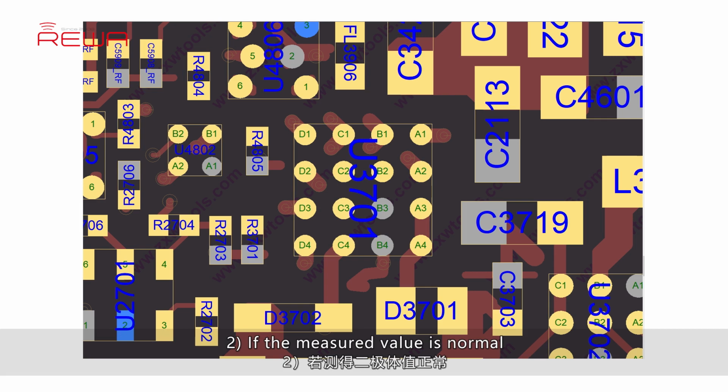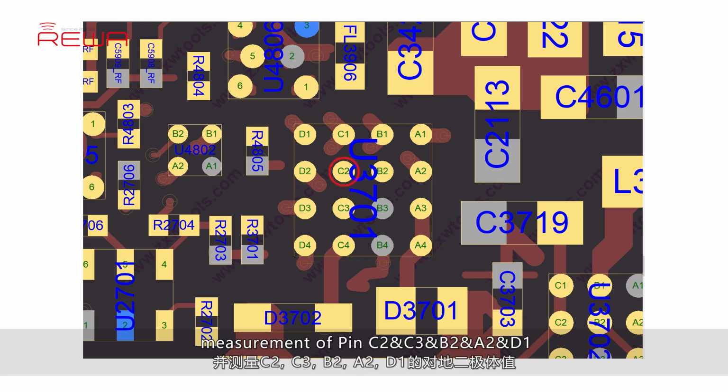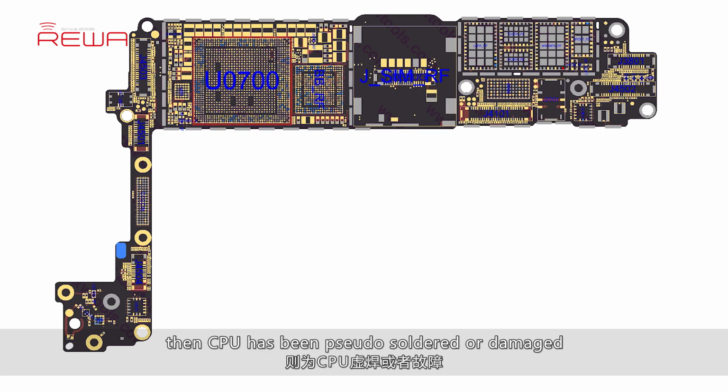2. If the measured value is normal, detach U3701 from the board and run diode mode measurement of pins C2 and C3 and B2 and A2 and D1. If the measured value is normal, we need to replace U3701. If the problem still remains unresolved, then CPU has been pseudo-soldered or damaged.